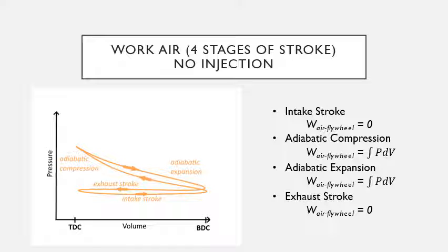In the compression stage, work is done on the air equal to the area under that section of the curve. However, in expansion, the air does work also equal to the same area as it retraces its path on the PV diagram. The total work done during compression and expansion is represented by the highlighted section on the figure, but ideally this sliver of work is actually close to zero and considered negligible.